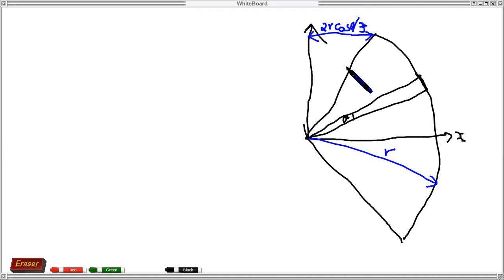Basically, it's the same thing again, because all they want you to find is the x centroid. So you can put up your equation here. X bar is equal to, again, the integral of x_c dA divided by the area, because this is not a regular shape, so you can integrate that portion to get the area at the bottom.